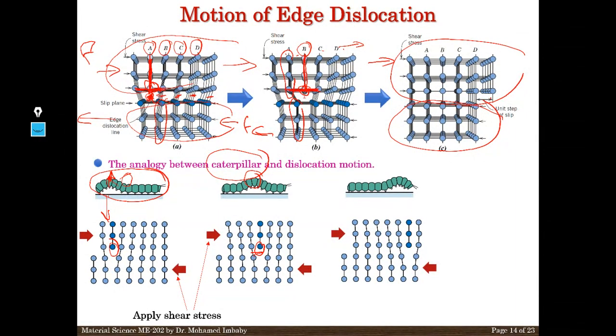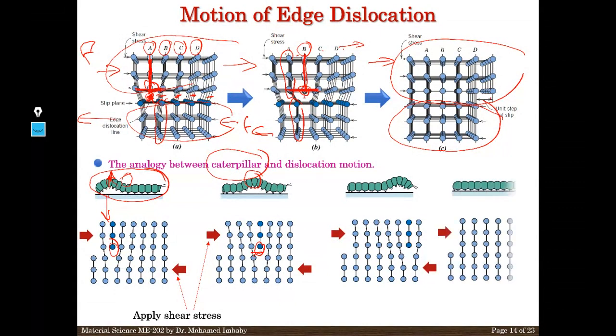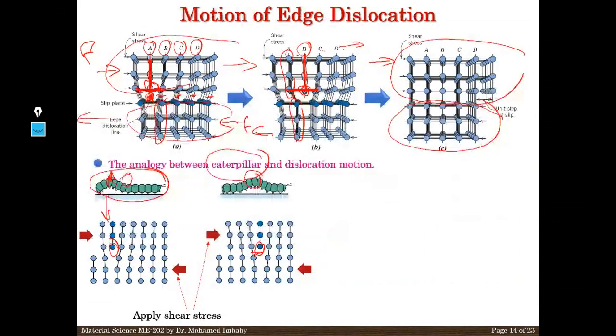So here it is very important to understand that dislocation is very important for the deformation of the material, because it makes a slipping, as you have seen here. I explained it in that graph. It is needed to move the atoms from one place to the other. If there is no dislocation, the deformation is very difficult, and when it happens, the material breaks without deformation. Okay, I will come back because I need to say the conclusion here.